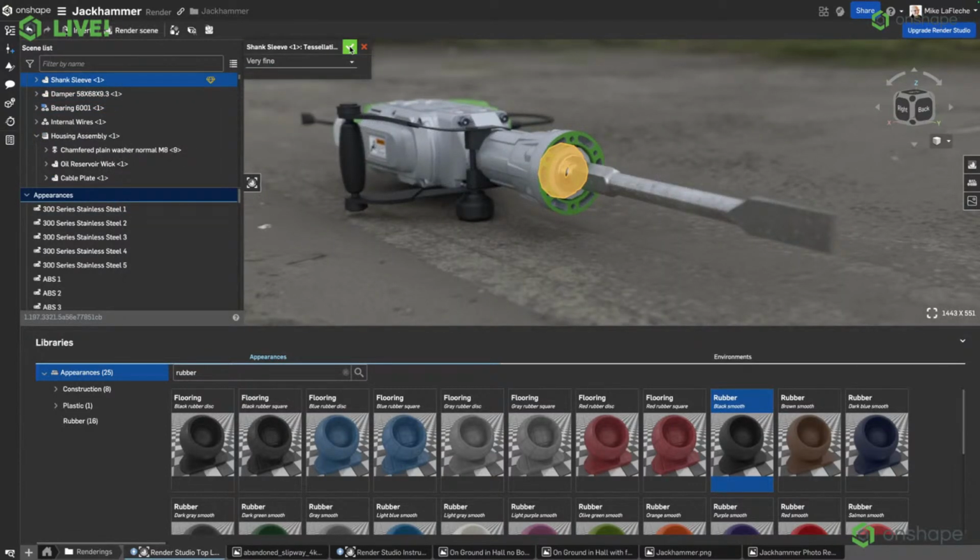I mean, I could have done the whole thing, but it's not really necessary. It's just going to add calculation time to your rendering. That doesn't need to be there. So just pick the big round parts that look a little jagged, increase the resolution on those, and you'll be good to go. So I have a pretty good looking photorealistic rendering almost right now, but you want to hit